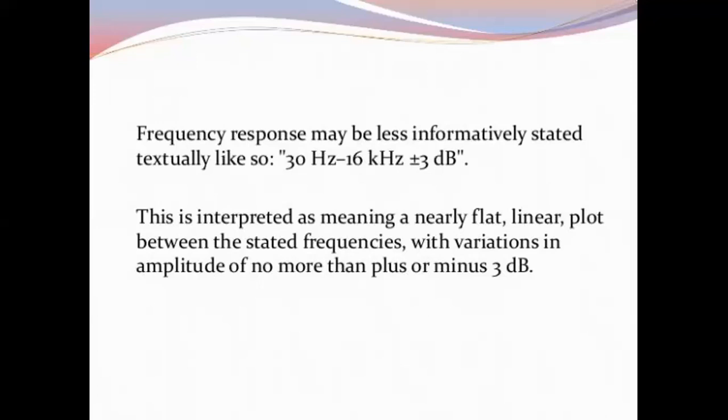Frequency response is the steady state response of a system to a sinusoidal input. In the frequency response method, we vary the frequency of the input signal over a certain range and study the resulting response. For a good frequency response, headphones and microphones are considered very good. Amplifiers, CD and DVD players, and other strictly electronic devices should be within 1 dB at most.